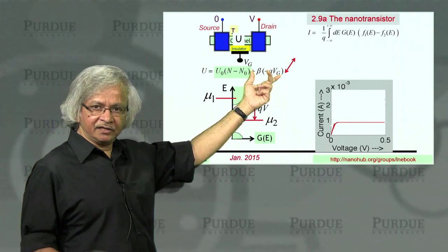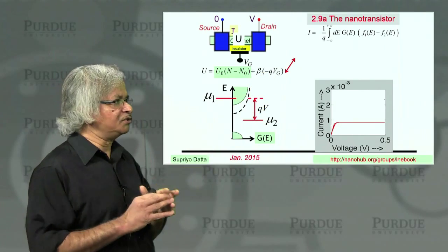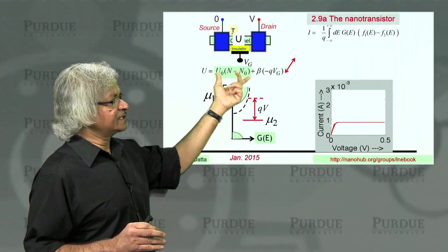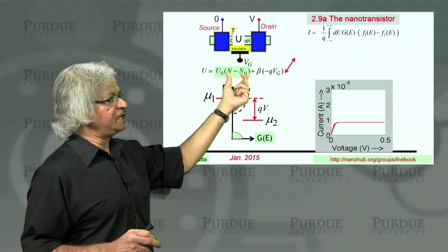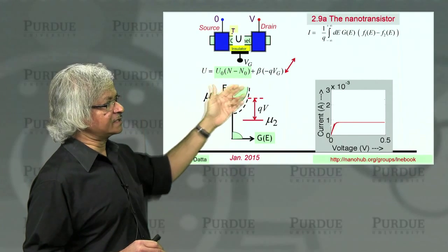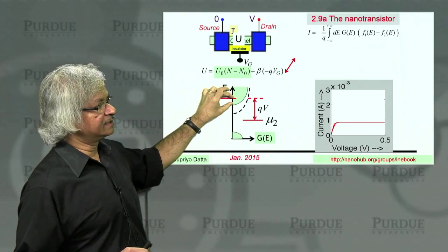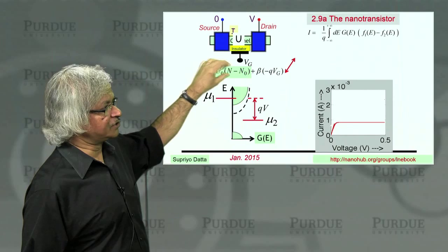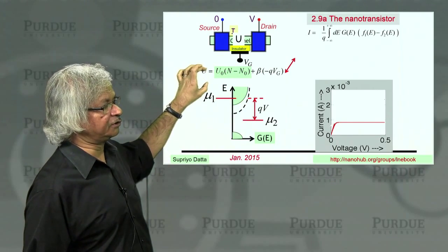something that depends on the gate voltage like we did before. This term doesn't matter here because we are assuming a fixed gate voltage. And then there is this term which is this charging energy, this U0 times the change in the number of electrons. And this is the quantity that when you apply a bias, what happens is the number of electrons goes down because these states used to be completely full, now they are half filled. So this goes down and so this becomes negative and as a result pulls it down. So mathematically that's how it would enter.